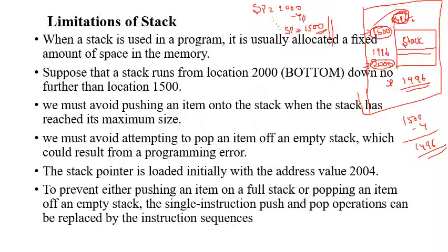The data present in this location will be stored in some register, and during the pop we know that it will retrieve the data, then add 4 to the stack pointer. So 1996 plus 4, the stack pointer value becomes 2000. If you further pop the data, it will pop from an empty stack, which gives rise to a programming error.